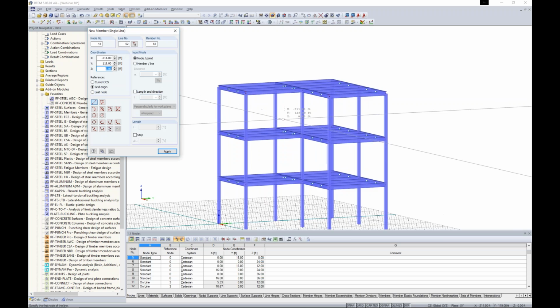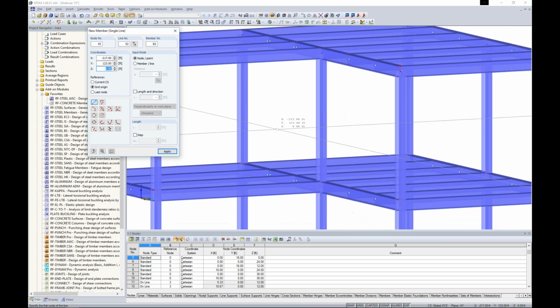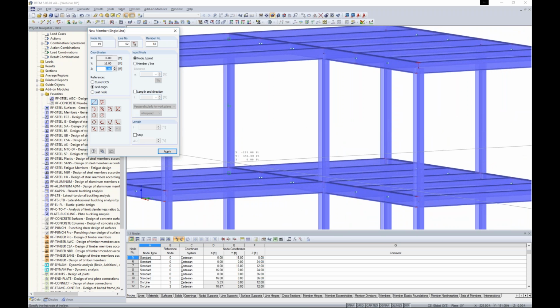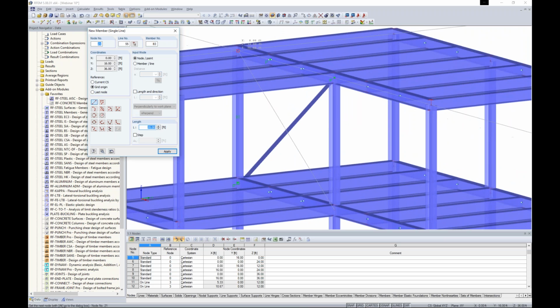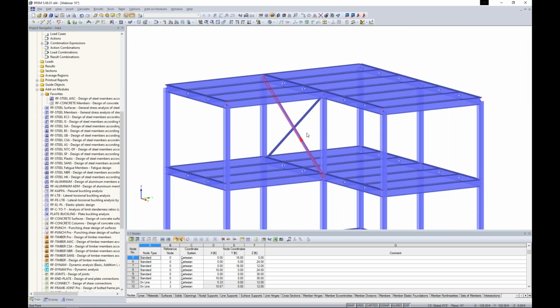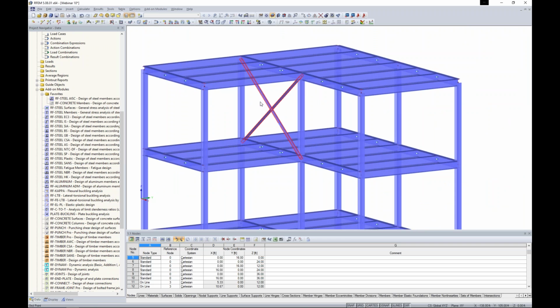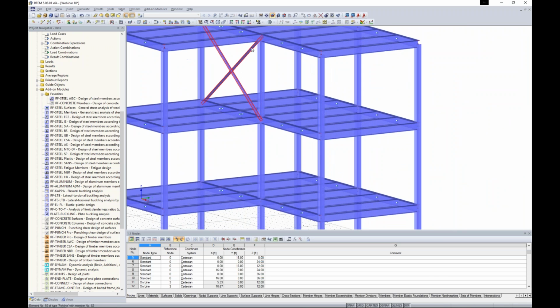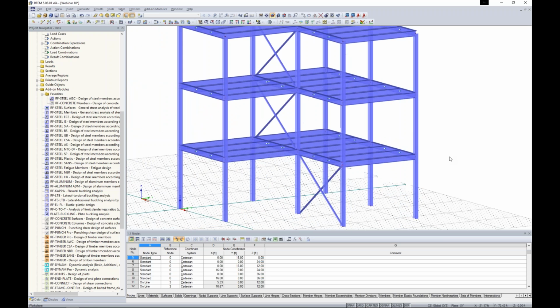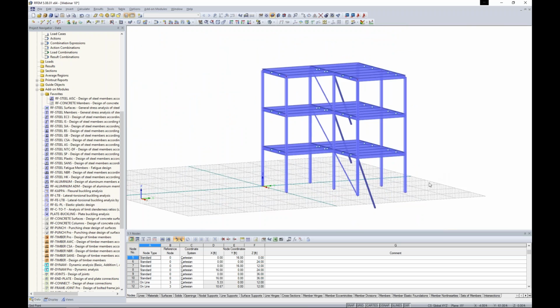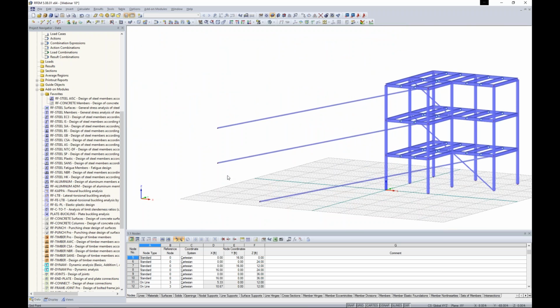We click OK, and now we can zoom in here and we can snap to our corner points where we'd like to add in this bracing. So once I have these two braces modeled, I can use my selection tool and utilize that drag and drop feature to add some additional bracing to the structure. And basically, looks like we have some mistakes here.